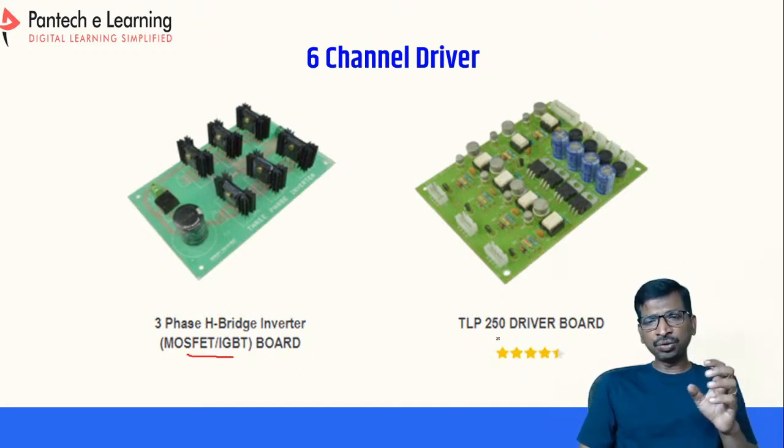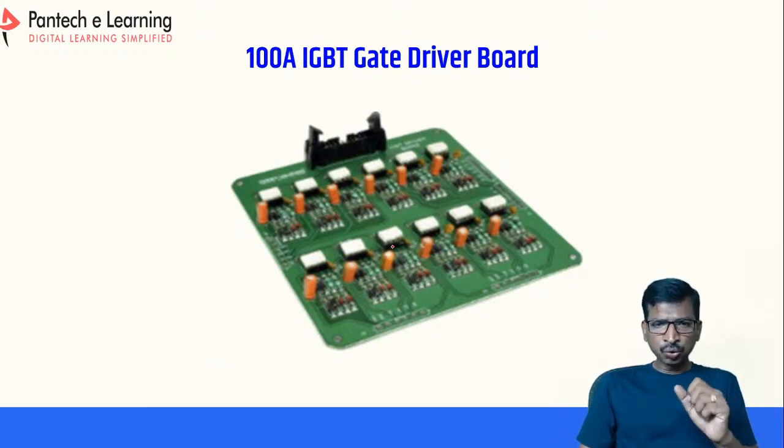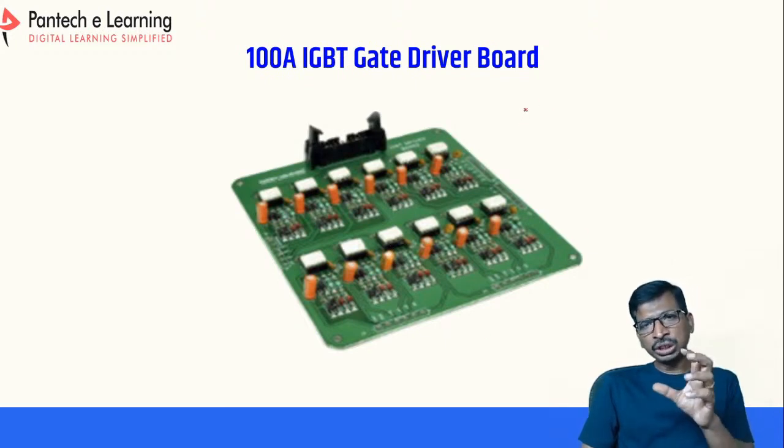And then the TLP 250 driver board. And the 100 ampere IGBT gate driver. If you want to handle 100 amperes, then you have to use this kind of driver, because this driver will enable negative voltages to ensure the turn off of the IGBT.